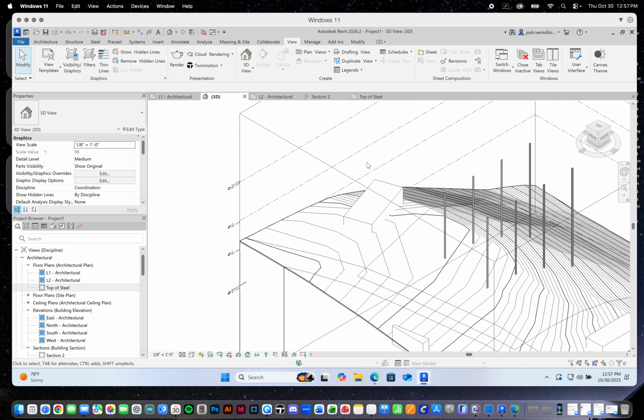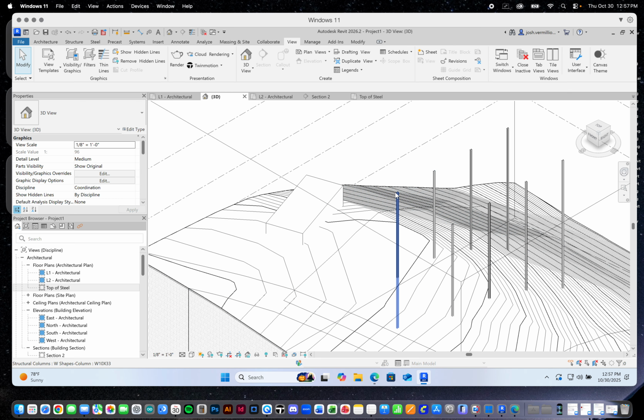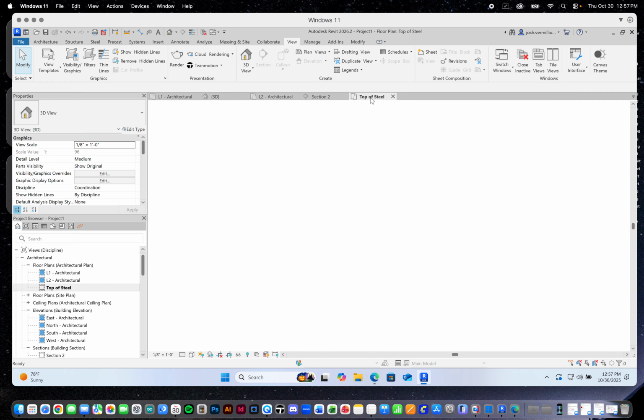Right, so what I'm going to do is make these along the top. I'm going to make beams that span 36 feet from east to west between column and column. And then I'll do the 24 footers spanning north-south between columns, over the 3 bays that we made north-south. So let's go to our top of steel.